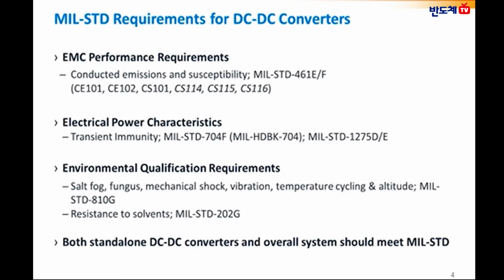Emissions or noise is internally generated in the switching power supplies as a nature of their operation of the circuit, as well as the result of parasitic capacitances formed in the circuit. The conducted emissions are the internally generated noise that propagates back onto the power supply through a conductive path. Thereby, the noise is transmitted to the devices that are connected to the same power supply and also can interfere with the close proximity devices.